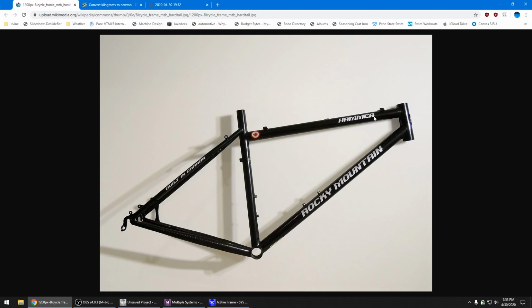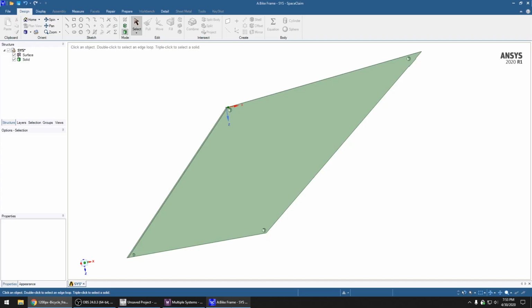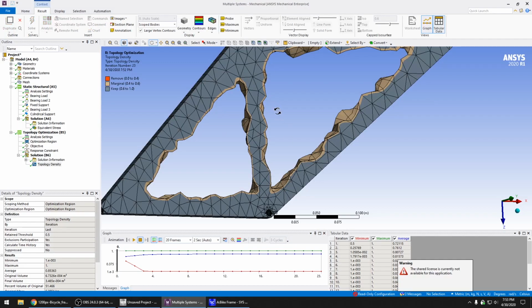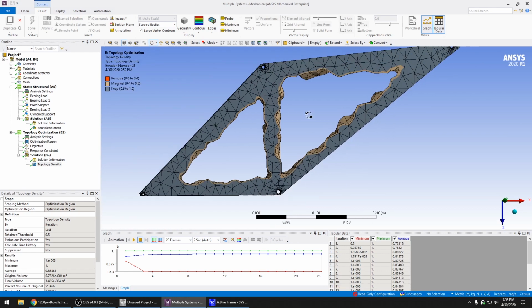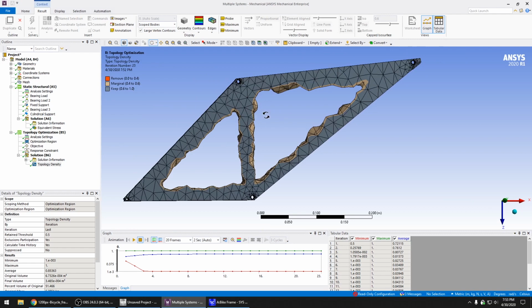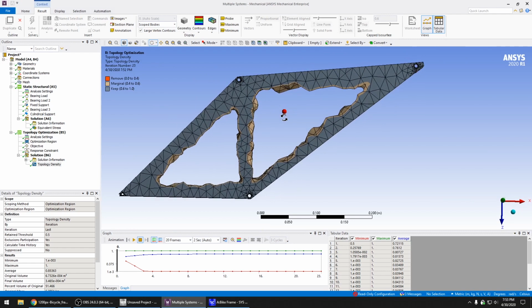It's pretty simple. You just take a pipe, another pipe, another pipe, some slightly different pipes which are flattened in certain areas, a smaller diameter pipe, and a little piece of metal, and you just weld it at all the joints. And it's, well, not very easy, but relatively manufacturable. If I gave you a sheet of metal and I told you to make this shape, it'd be very difficult. So unless we 3D print it, which is very hard to do with metal, it does exist, but it's expensive, this is hard to make.